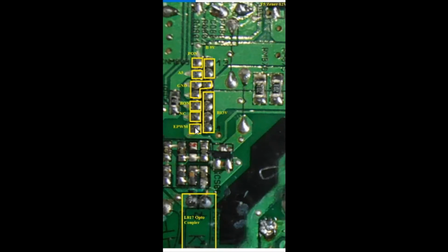And this is the interesting thing: this is the kind of PWM input taken from the remote controller, because in the remote controller we change the brightness from some controls. That comes as a pulse width modulated signal, and that gives the input to this television, and the television's video controller, not the LED driver, controls the required brightness level via this.